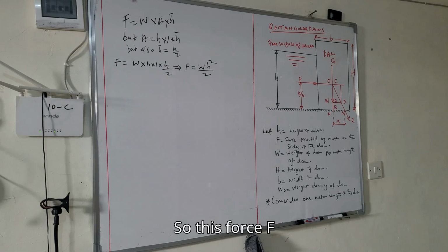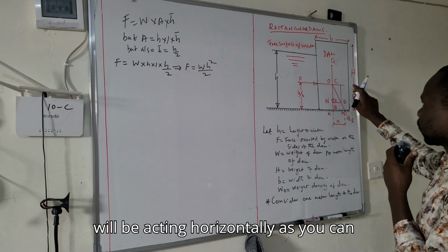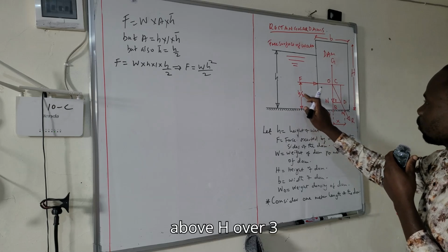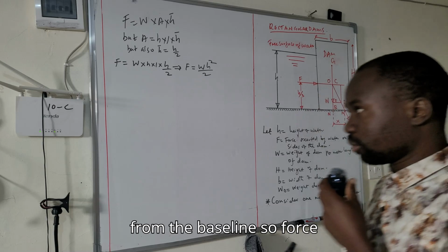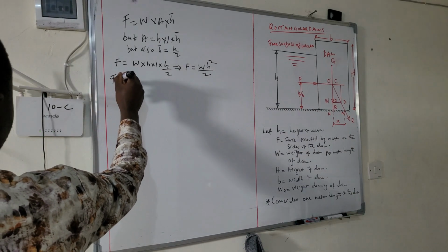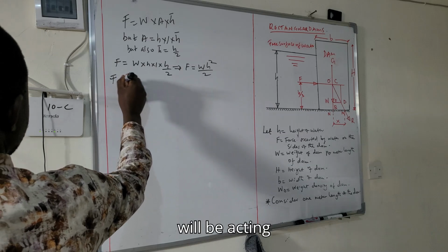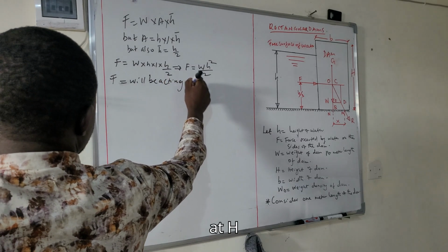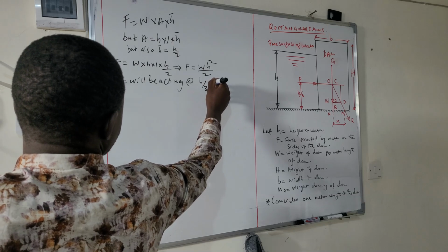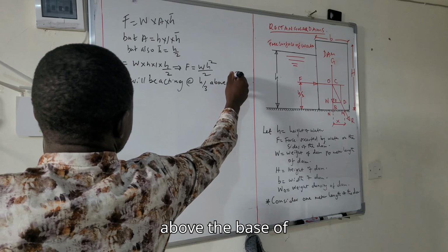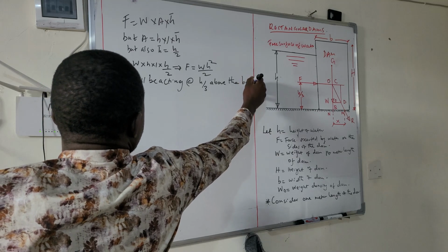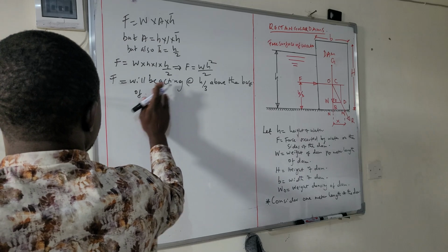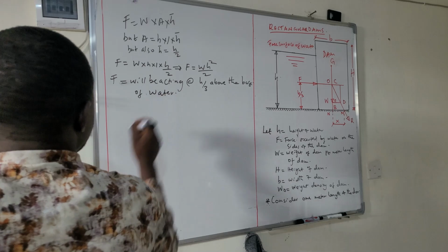This force F will be acting horizontally, as you can see, at H over 3 above the base of water, like that.